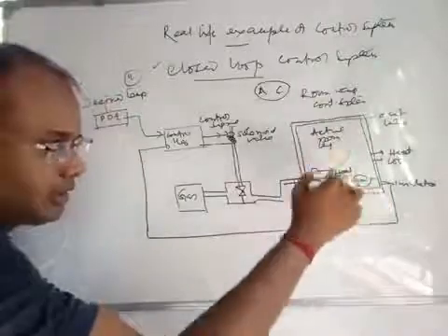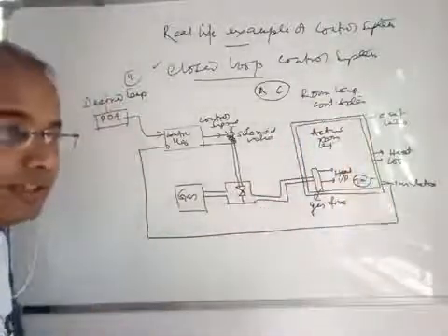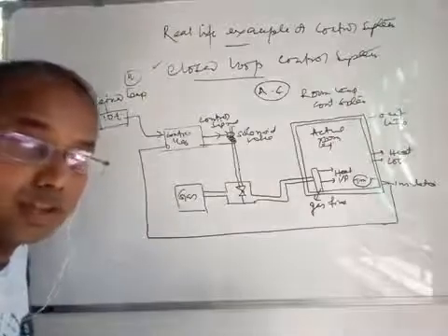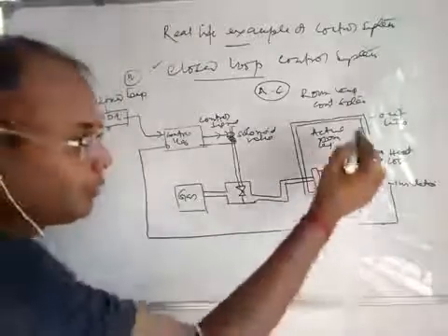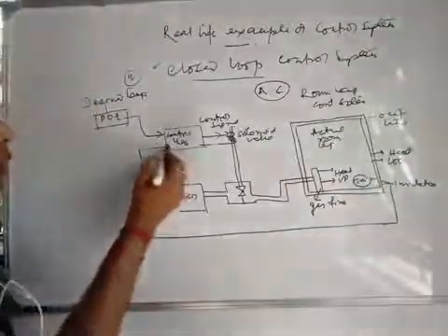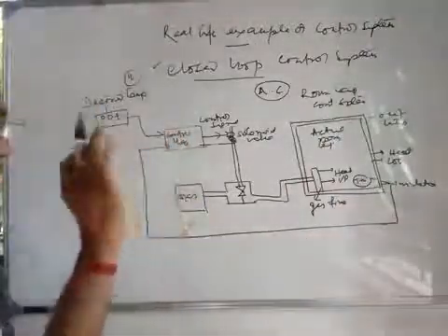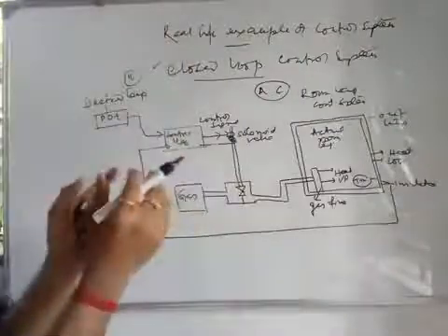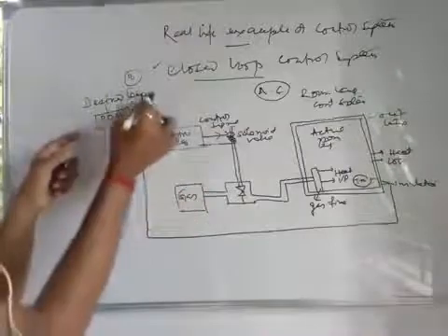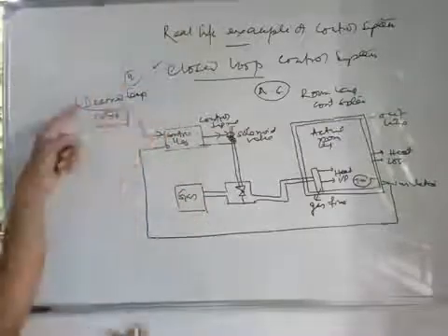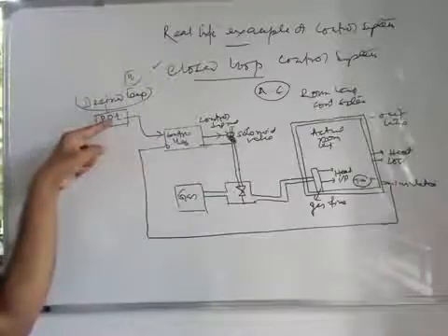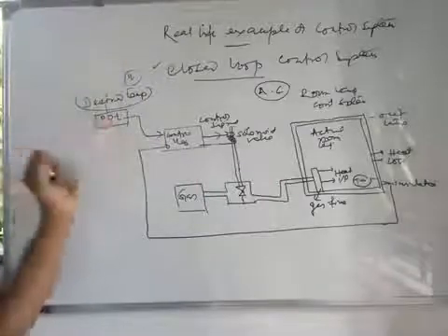Now this is perfectly insulated. That is the balanced condition, and that is one of the most important conditions to be followed, because this temperature is the feedback part, right? This goes to the controller, and if you relate this generalized block diagram to this system, this is your desired temperature, which is normally converted into voltage by using some potentiometer.